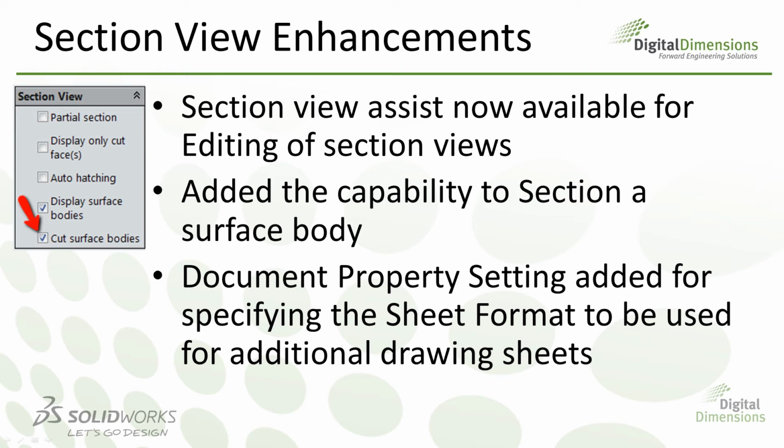And then the next thing to mention here is there is a new document property to accommodate your next sheet title block. So in other words, in the past, when you generate a new sheet, well, for starters, SolidWorks added a setting that turned off showing the sheet format dialog on Add New Sheet, which always confused me, so I always tell my classes where to turn it back on, because most companies use a separate title block for Sheet 2 anyway, so having that toggle was kind of confusing.